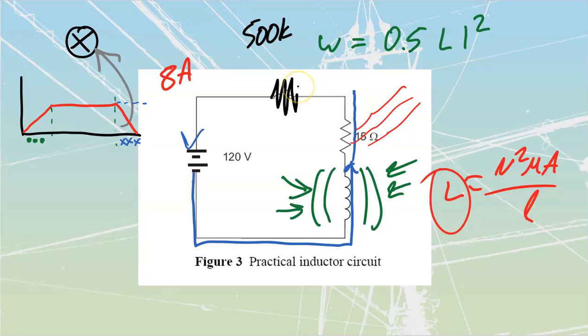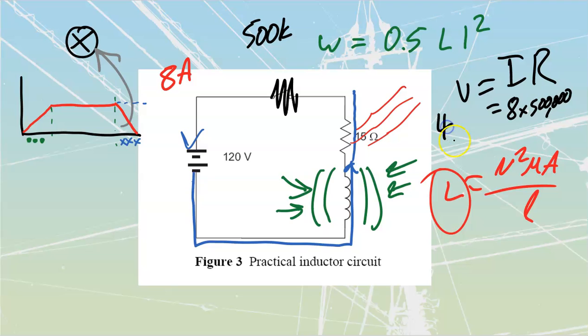Well, if we're going to work off of Ohm's law, which we always do, V is equal to I times R. What it would need to do to overcome 500 K ohms at 8 amps, 8 times 500,000, is going to be a value of 4 million volts. We call that 4 megavolts, MV. That is a phenomenally high value of voltage. Obviously, this is going to be dangerous. I mean, nobody wants to get hit by 4 million volts over here.